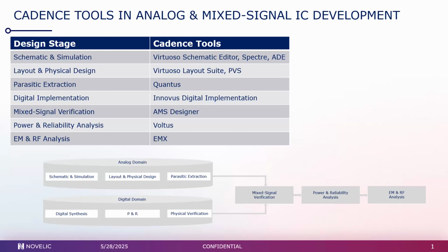Usually that is some worst case scenario. And then Voltus is doing analysis of the layout and provides us a great overview if any line is critical, if we have electromigration issues somewhere, if we have IR drop, internal resistance drop anywhere, if we have too much parasitic inductance anywhere. So overall, it is a great tool for power analysis and reliability analysis.